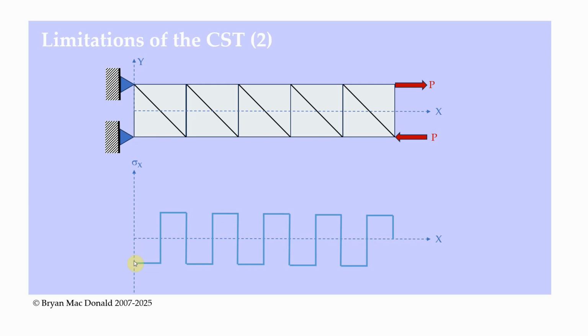Okay, so we're going to get a compressive stress until we move to this point here, at which point it's going to abruptly change to being tensile. Okay, so that's what's happening here. We're getting compression here, abrupt change to tension, an abrupt change down to compression again. So think about it as we move along here. We're compressive in this element. This element is going to be tensile. This element is going to be compressive, and so on.